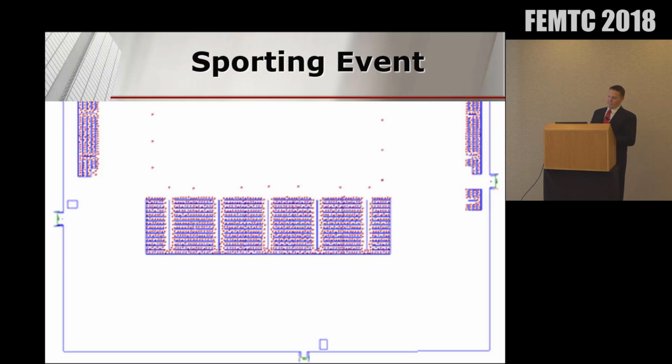So here we have some bleachers. One of the challenges with bleachers is the exits are on the sides, and like on the airplane, the nearest exit might be behind you. But in this case, the occupants will tend to move laterally through their rows. And so this center aisle would not be used for an evacuation because it's not along the shortest path. Well, that's illogical, so we can fix that. There's a gap here near a door. That can create a problem for occupants who think that's their shortest path, but then they don't fit.